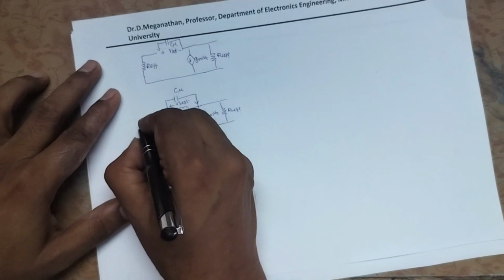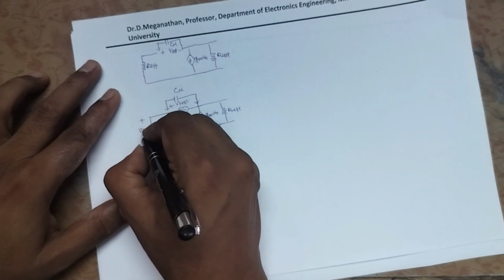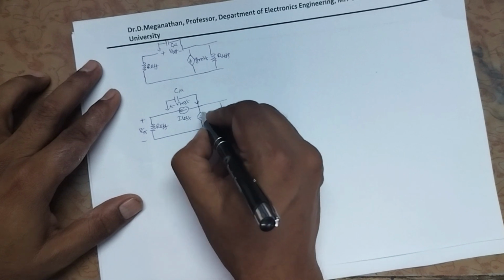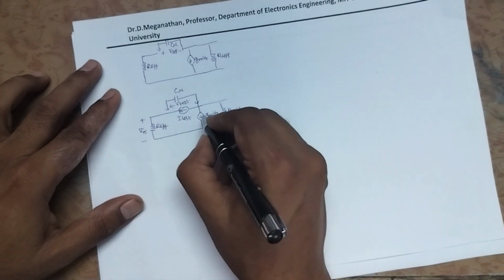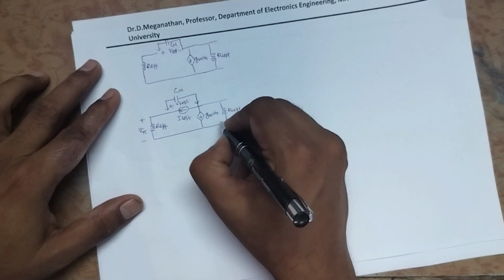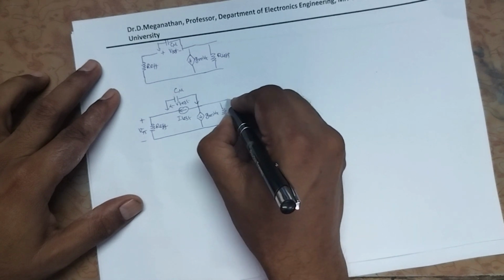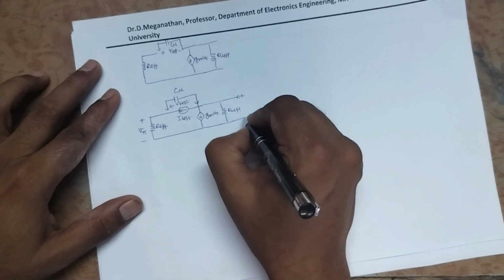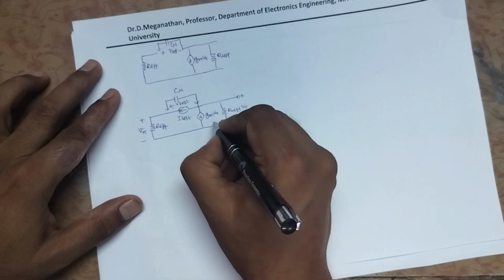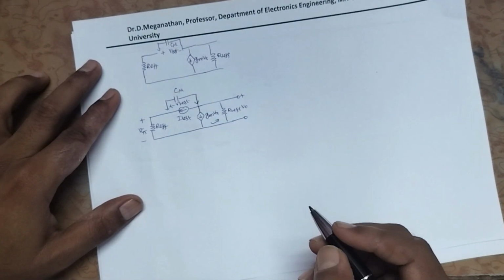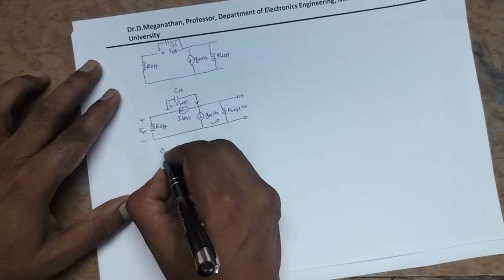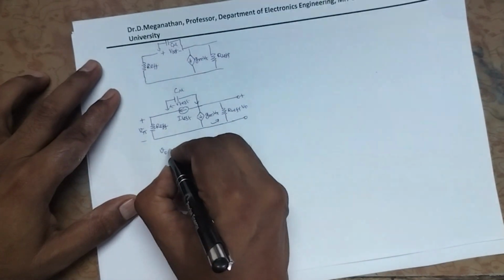Okay, when I test current flows, it makes a drop. Let us name it as V pi. The Gm V pi is the dependent current source at this point. So it makes the drop of V naught, but we assume the drop across the RL effective is V naught. This is the actual current flow. So we can say what is V naught? V naught is the drop across RL effective.